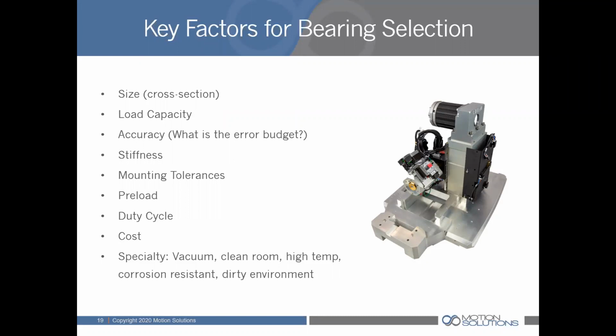Remember that the calculation is the dynamic load capacity divided by the load to the third power. So as you increase your load capacity of the bearing, you're greatly increasing the fatigue life of the bearing. So you can kind of do a quick calculation when you're selecting a bearing. Do a quick calculation of what you think the resultant loads on the bearing will be, and see if that's going to meet your life requirements.